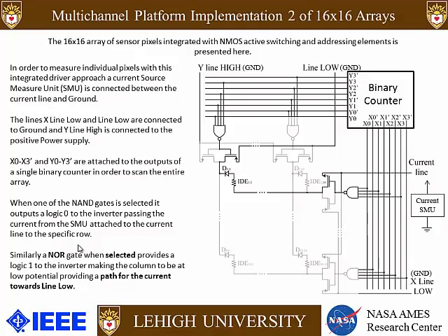So this has a little bit less sensitivity, as you can imagine, because we have 3 active elements, the diode and the 2 transistors connected in series, and actually the PMOS, as always, has lower mobility, so that creates higher series resistance and other issues. But still, this setup works, as I will present to you some data later.